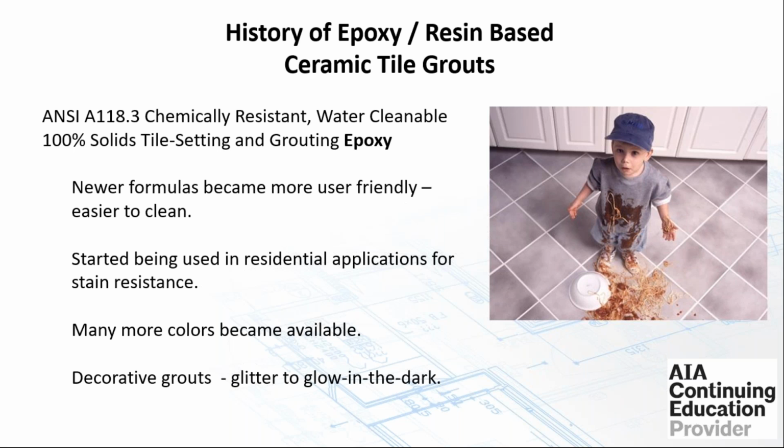As I said, we see more and more use of it in residential because of its stain resistance. If you've picked a very light colored grout in your residential kitchen, you don't want it turning dark over a period of time, so using an epoxy will help prevent it from staining and turning dark on you. Of course, many more colors are now available, and we've even seen decorative grouts where some companies offer glitter and glow-in-the-dark type grouts with the epoxy grouts. So a lot of variations, a lot of applications in selecting an epoxy grout.